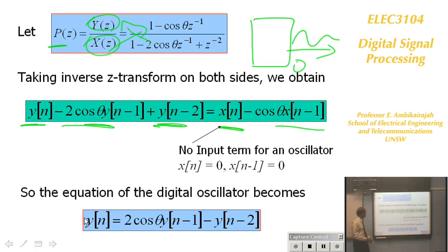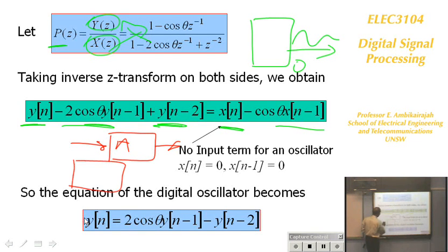That's your oscillator. Now, the question is this: when you have a signal generator, take an amplifier. If you've got an amplifier, you get an input and an output. You give an input signal, it's amplified, and comes out. But when you have an oscillator, there's no input as such. You just turn on the system, it oscillates. It gives you an output, a sine wave.